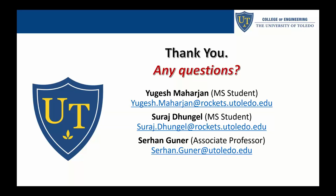Yeah, definitely. If you are using modified compression field theory, you need to calculate epsilon x, and in the denominator of the epsilon x calculation, you need to consider the longitudinal reinforcement and its conditions. So it's part of the procedure. It needs to be considered if you are doing it according to modified compression field theory. Yes, Dr. Guner, that is correct.